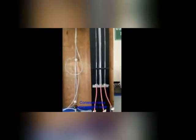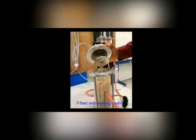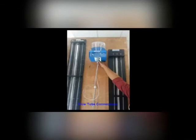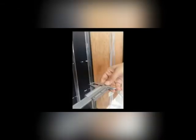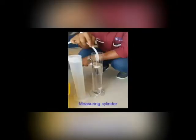I will talk about the equipment of this project. This is the constructed falling head permeability cell. To set up this experiment, we need a few pieces of equipment. First is the cell fitted with loading piston. Second is flow tube connections. Next is vernier caliper, ruler, stopwatch, and lastly, measuring cylinder.